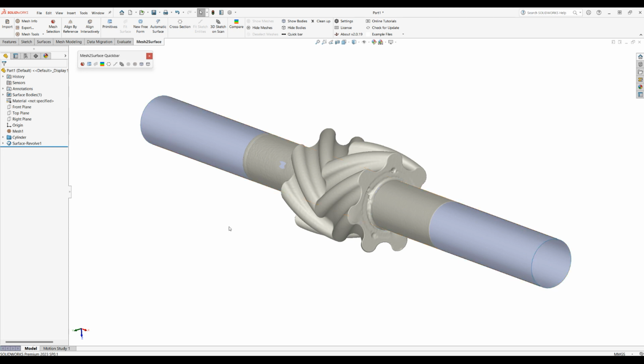If you want to get this mesh flattened, we provide a tool called Unroll. It's located in the Mesh Tools menu. You need to pre-select the mesh to make sure that the menu has all the features, and then you can select the function called Unroll. In order to unroll our mesh, we need the cylinder, and that's why we created one.